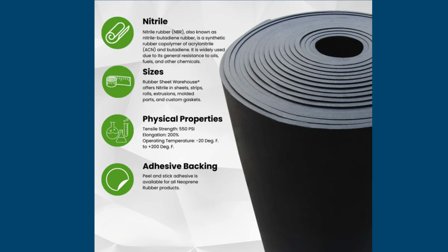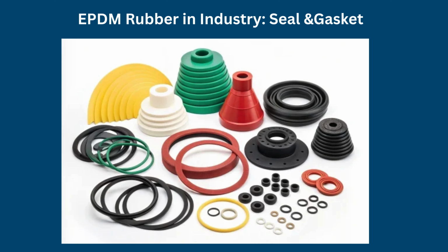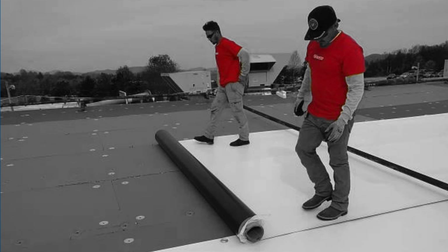Ethylene propylene diene monomer, EPDM, rubber is synthesized by coordination polymerization of ethylene, propylene, and a small amount of non-conjugated diene. The saturated ethylene-propylene backbone provides exceptional resistance to oxidation, ozone, ultraviolet radiation, and heat, while the residual diene units permit sulfur vulcanization. Consequently, EPDM has become indispensable for automotive weather seals, roofing membranes, and electrical insulation.